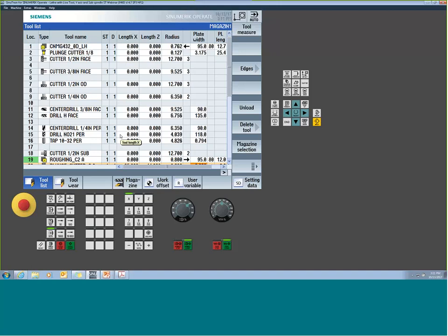If it's here, mill or lathe, it does support it. Now in the lathe, it's important that you pay attention to this. In the lathe, FANUC actually has 3 different protocols of G-code. And a lot of people don't realize this. A lot of people think, oh, it's a 6M or it's a 6T or a 0T, it's a 21I. That doesn't mean anything.